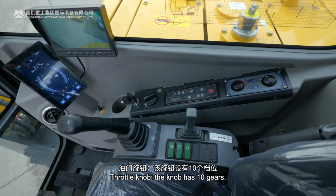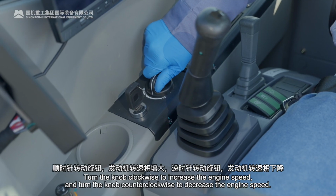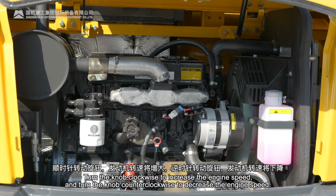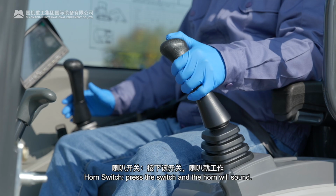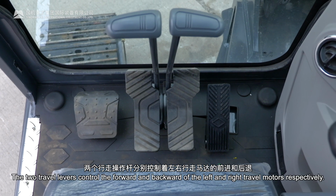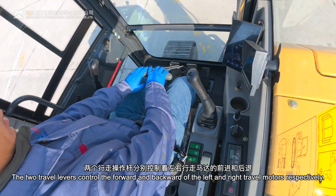Throttle knob. The knob has 10 gears. Turn the knob clockwise to increase the engine speed, and turn the knob counterclockwise to decrease the engine speed. Horn switch. Press the switch and the horn will sound. The two travel levers control the forward and backward of the left and right travel motors respectively.